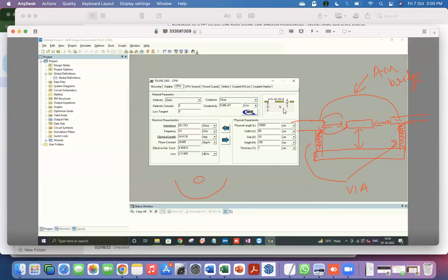Right now, this substrate just looks like a slab of dielectric with some metal patterns on the top, right? One can make this, but usually these kinds of structures sit on some other box, which is usually metallic. So not having a coating of metal underneath the chip is of no consequence if that chip is sitting on a metallic piece, because then that gives you the ground plane.